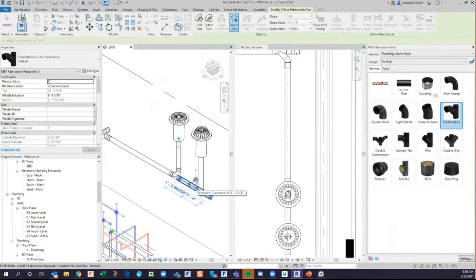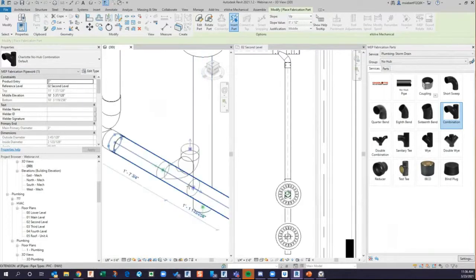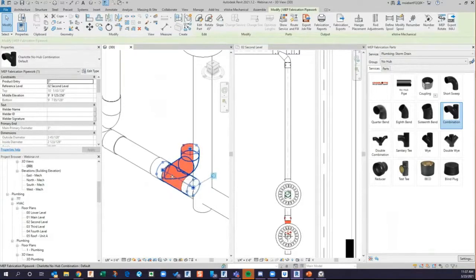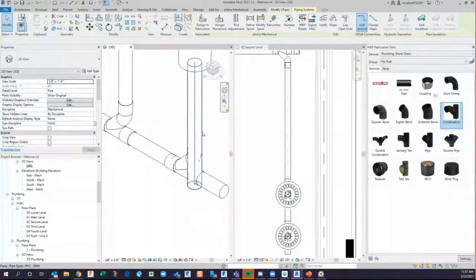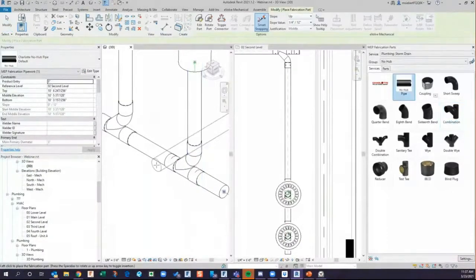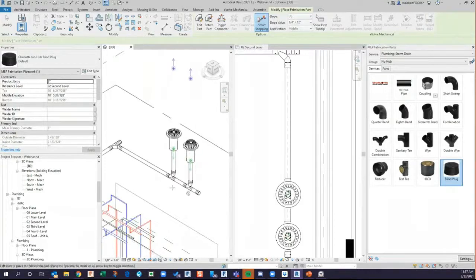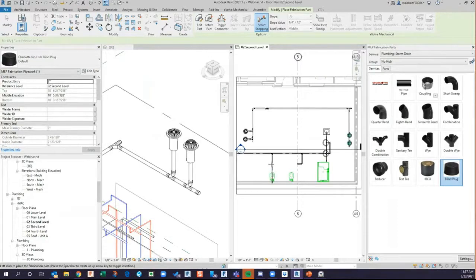I'm going to get this in an upright position, drag it into place. Snap on that pipe. Click on that. Now I'm going to move this. I'm using my down arrow to move in an isometric mode. Once I've got it lined up, I'm going to get rid of that pipe, put another piece of no-hub in, let it run all the way up so I'm coming through it, and put my clean out right there with my plug. And now I'm in a position to draw in hangers and get the rest of my pipe converted. So that one took a total of 5 minutes.